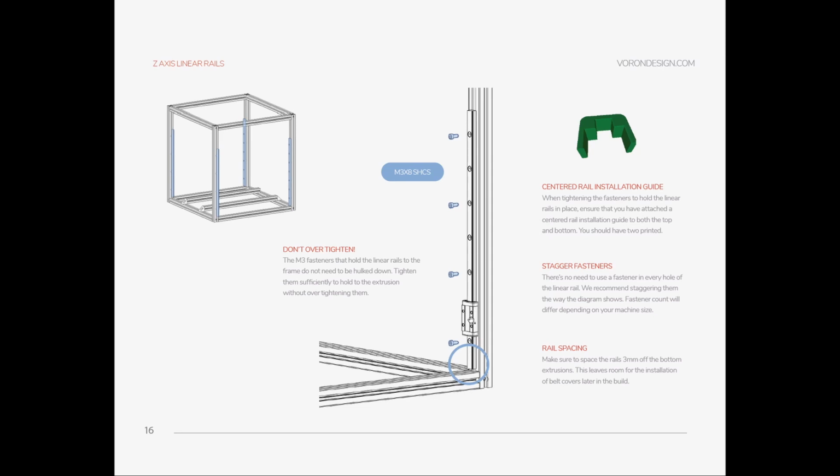You don't need to disassemble the carriage. I just applied a bit of grease where the balls are, at the back of the carriage, and ran the carriage back and forward, and keep this process until you are happy. Also, you can apply it on the rail, but it's a little bit time consuming, but it's required.